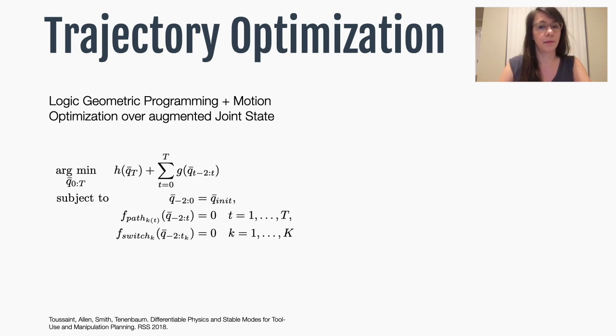And basically, Marc Toussaint and co-authors, they have formulated this optimization problem in the way that I've already shown you. And specifically, they sum the trajectory cost across all time steps that results in a banded Hessian that can be inverted efficiently with Gauss-Newton methods. And I want to also emphasize that the minimization is actually over a joint space trajectory.